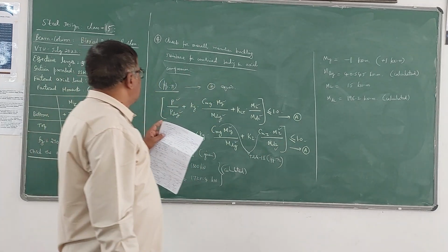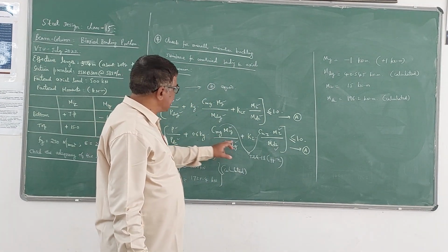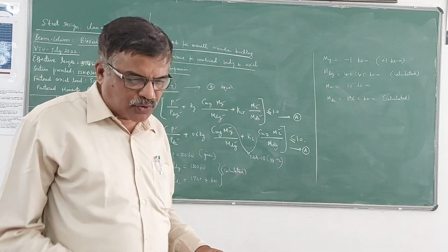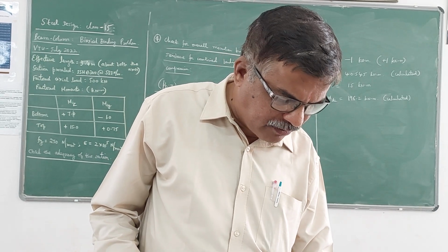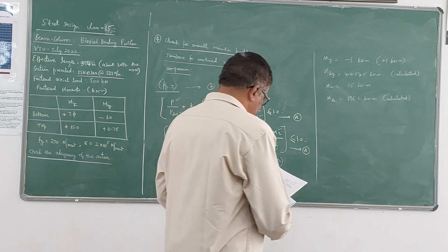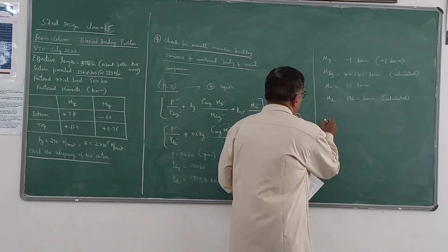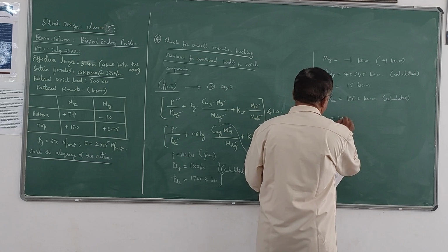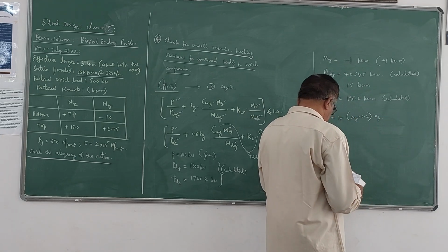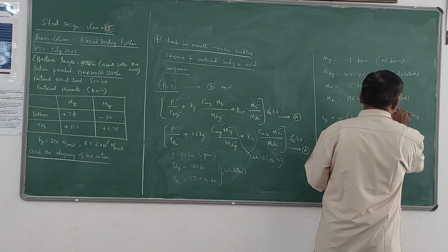Now the unknowns are KY, KZ, CMY, CMZ. So these are the unknown values. Let us see how we can compute them. For finding KY and KZ, the equations are given on the same page, page 71. See here, KY is equal to 1 plus lambda y minus 0.2 into ny, which should be less than or equal to 1 plus 0.8 into ny. So this is a check for that.